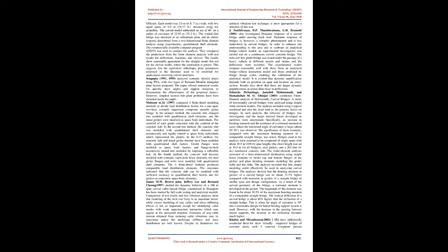Dynamic response of bridges is, however, a complex phenomenon and is less understood in curved bridges. In order to enhance our understanding in this area and to calibrate an analytical bridge vehicle model, an experimental investigation was carried out on a continuous curved concrete bridge. The twin-cell box girder bridge was tested under the passage of a heavy vehicle at different speeds, and strains and deflections were recorded. The experimental results compare reasonably well with those from an analytical bridge vehicle interaction model and those predicted by bridge design codes, enabling the calibration of the analytical model.